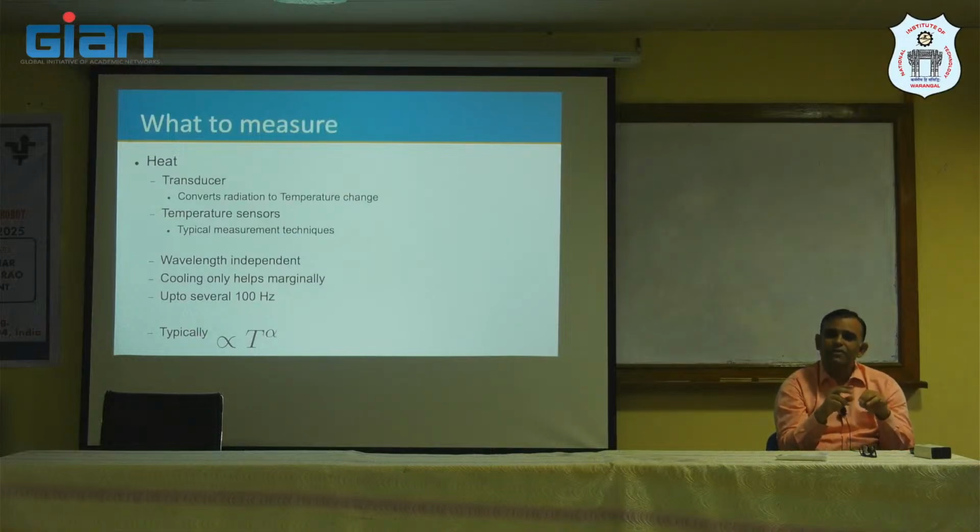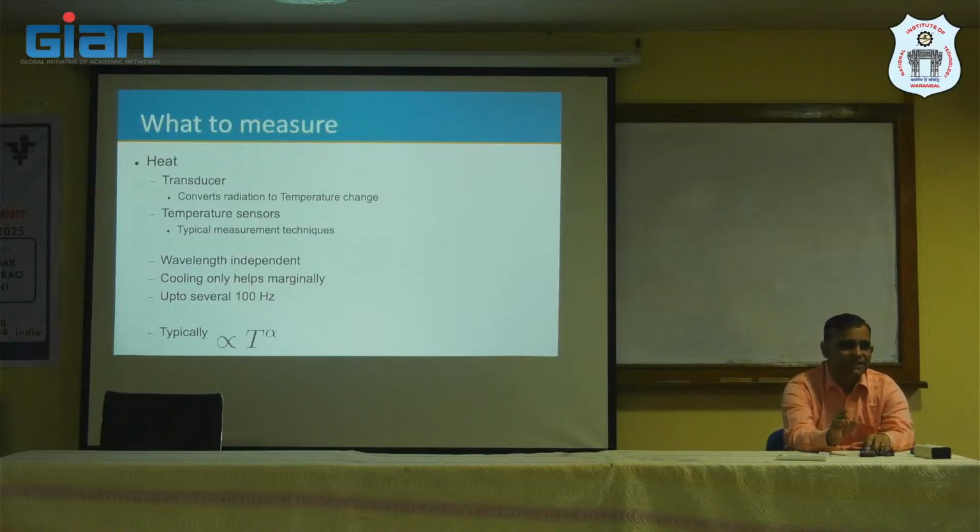So ambient heat produced electron hole pairs are like noise to me, or my leakage current. Even in photodiodes, in pixels, heat produces electron hole pairs. So one solution to that is to cool the sensor. Now, this is particularly when you are trying to record very low amounts of intensities.